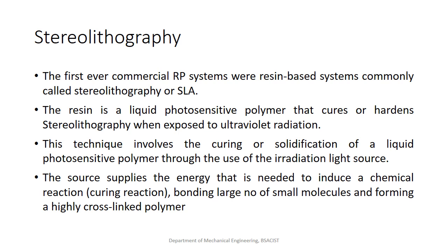The resin is a liquid photosensitive polymer that cures or hardens when exposed to ultraviolet radiation. This technique involves curing or solidification of a liquid photosensitive polymer through the use of an irradiation light source. The source supplies the energy needed to induce a chemical reaction, which is called a curing reaction, and the body of a large number of small molecules forms a highly cross-linked polymer. So finally we get a solid surface from liquid.